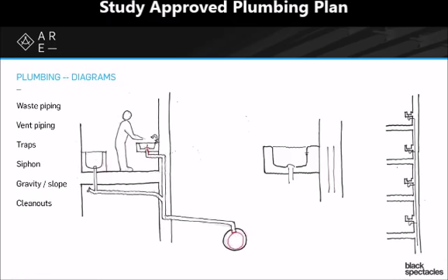What would be the obvious problem with this? Well, clearly the obvious problem is I'm going to be getting sewer gases right up from that pipe, straight from that sewer pipe in the street. There's air essentially filling most of this pipe until there's some wastewater that's flushed down it. So if that's just an open pipe all the way to the sewer line, that would clearly be a really foul-smelling element.